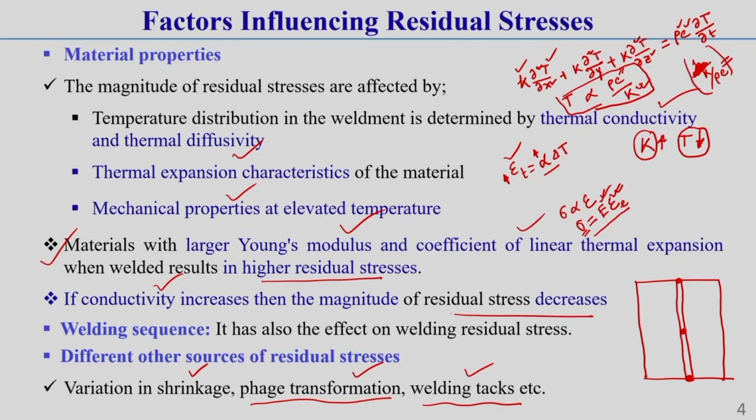As well, we want to make a T section, to position this T like this. This is one plate, over this plate we want to place another plate, correct. So another plate or bar you can say. This is the length of this plate bar. To align this T plate on this lower plate, it is required to put some tacking at the ends, otherwise this vertical plate will not be aligned on this lower plate. These are all called tack welds. So always you should keep it in mind.